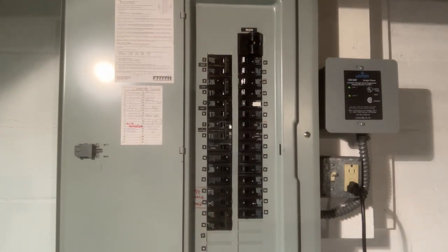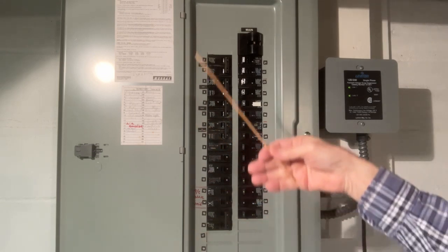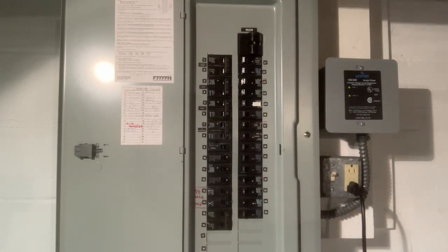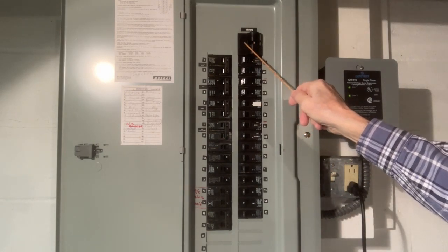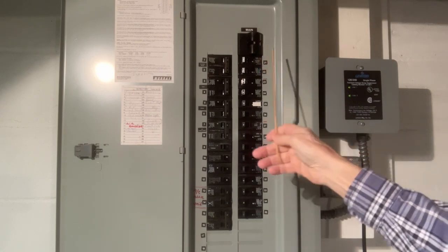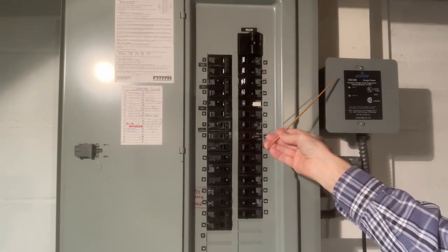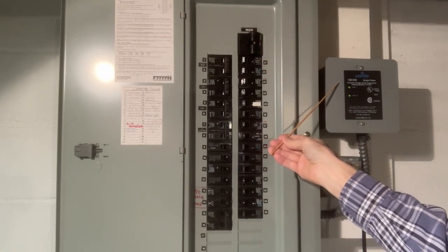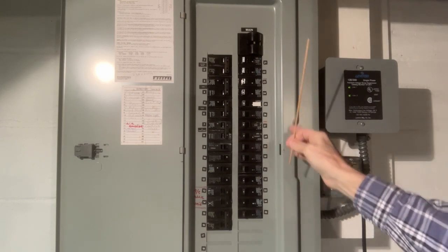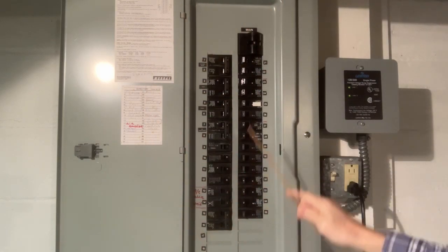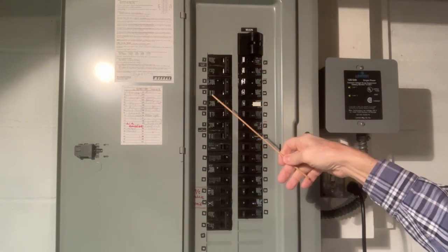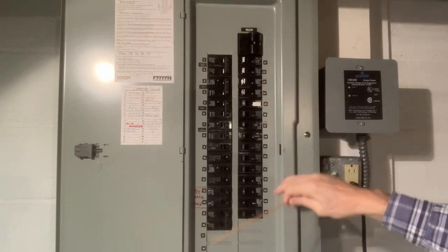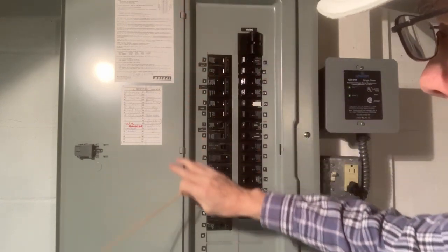Previously, when I talked about the protection features for the service entrance station or service station, I mentioned several. One of your protection features is your main breaker here, all right? And I just happen to have a surge protector, and most people nowadays will have to have this by code. All right, I have my surge protector, the grounding system inside. There's a grounding system that runs outside, and it runs over to my cold water pipe. And then, of course, there's the cover, the protective cover.